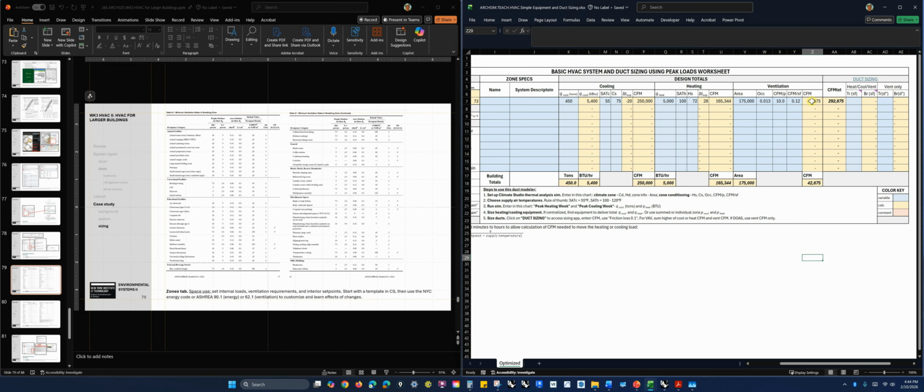So fresh air ventilation, I'm going to say always, always dangerous to say always, but always is a smaller amount of CFM than if we were moving heating and cooling in the air, and so therefore the ducts are going to be smaller. That might be a reason why you would decide not to use an all-air system, because you want to have a nice open CLT ceiling in all your floors, and you don't want to have a bunch of ducts up there. If you could design it to where you're moving heating and cooling not in ducts, like in refrigerant or in water, and then just have smaller ducts for ventilation, that would save you space, and that might fit your architecture better. In this case, though, we're doing both.